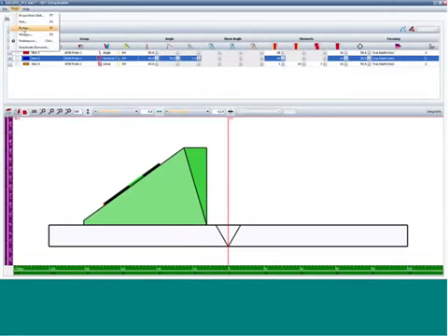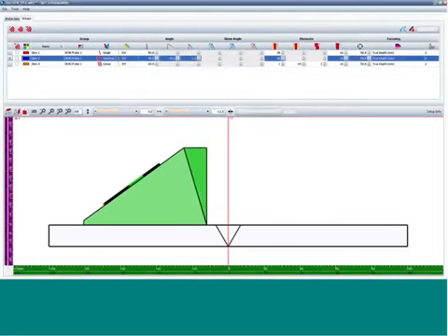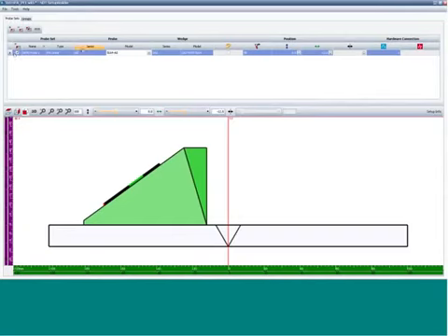Under the probe tab, we have similar information as the OmniScan database, and we can manage this directly here. Probes are added or removed, can be cloned and copied in reverse position directly on the interface. So this is a linear PA probe. TOFD and UT probes are also programmable. From the A2 family, it's the 5L64. The model number is entered here.